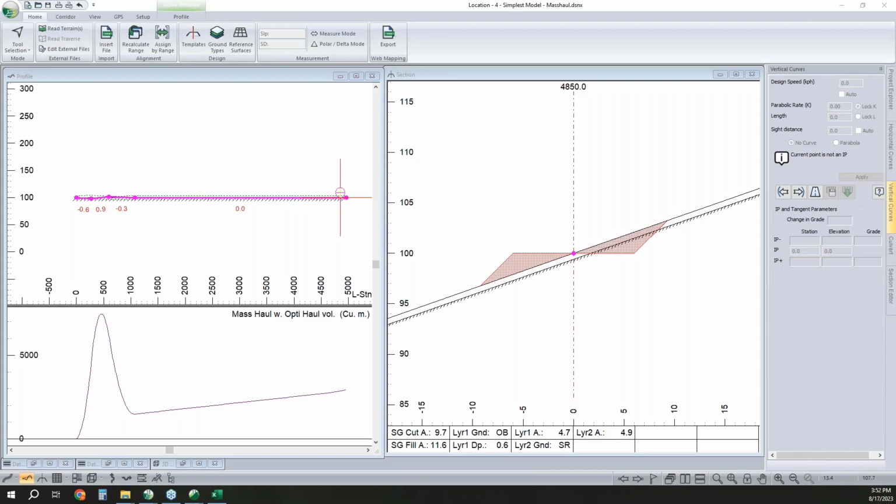Our ceiling for what's practical to design in our software is longer than most, but I'd consider chopping it up into 40 or 50 kilometer chunks rather than dumbing down the spacing. One strategy could be to do a high level pass with a sparser spacing and then add that higher density sampling in when you go to refine things.